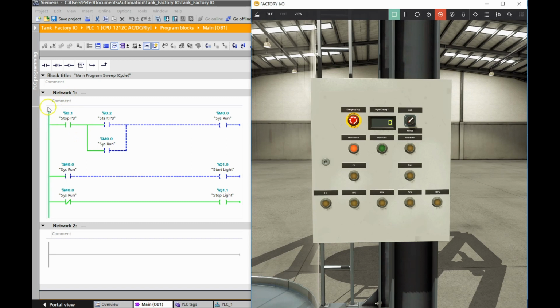Nice, we can see that we have logic continuity in that this is a 0 right now. So this is true. So that stop light is on right now. It will remain on when I press this push button, because pressing that push button has nothing to do with this guy right now. So right now it has no logic continuity to that M0.0. That M0.0 is off, so it's a 0. This is looking for a 0, so this is on right now.